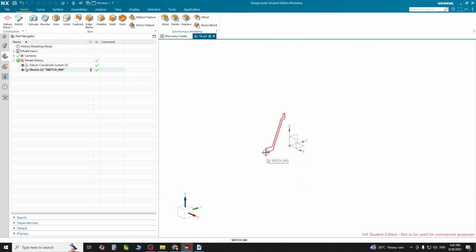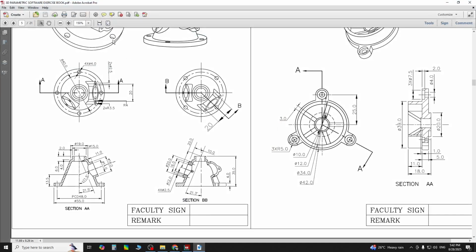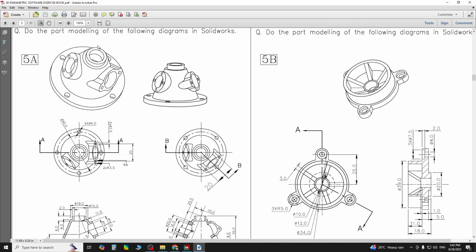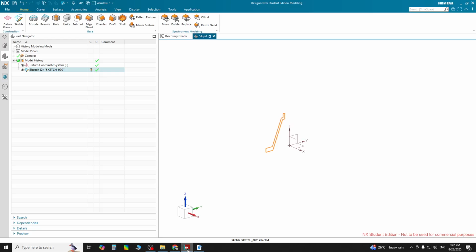Now the next operation is we have to transfer this to a solid, so next we have to create this round figure. To create this round body, we have to revolve this. This is just the sectional cross section part of that round model. If we rotate this cross section through this z axis 360 degrees, then we are able to create the 3D round model. So to create this we need to use this revolve tool.